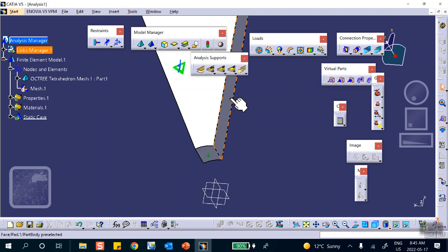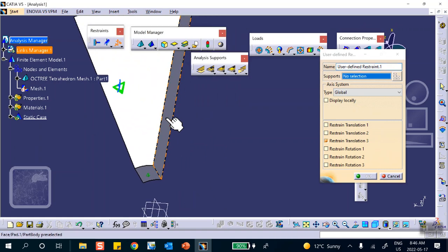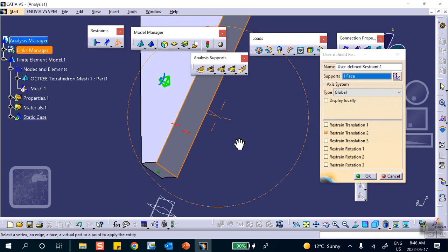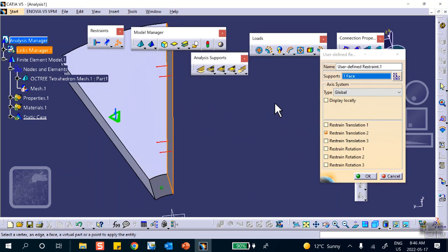You can do that. But in the book, on the other one, I didn't put a surface slider. I could have, and I will now. Okay, but this is obvious because nothing moves in the what direction would that be? If you look at your coordinate system in this drawing, nothing moves in the direction y on that face. And if I didn't like surface slider, if I had something against it, I can select user defined, and on that face, I say nothing moves in the direction y. Isn't that a surface slider? That's a roller. That's exactly as a roller. So I can do it like this.